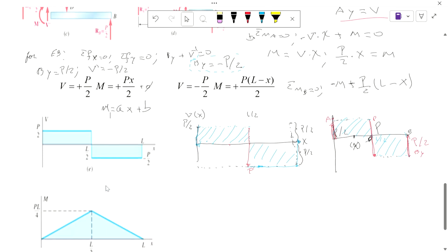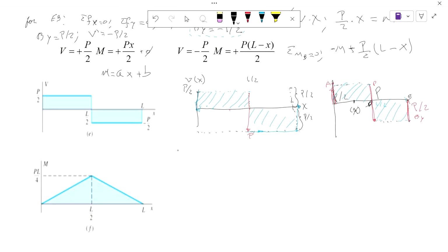So let's plot the moment. Again, you have three points you have to plot: A, D, and B. Please locate those on your x-axis. You have A, your point where the force is, which is D, and your point B. The way you do this is from your moment. C is very close to D, where we do the cut, extending to D, and that is Px over 2.